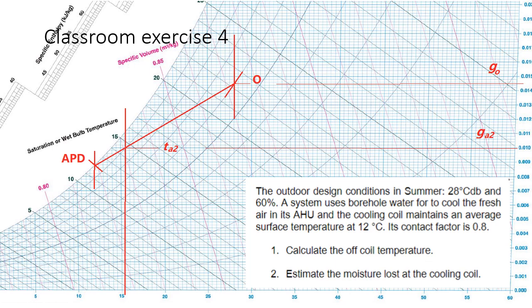Actually, the condensation happens. Now imagine if in this 28 degrees, 60% saturated, you take a can of beer out of the fridge, you immediately see the surface covered by droplets because the surface is much lower than 19 degrees, right? Anything lower than 19 degrees, you will see the condensation. So the surface at 12 degrees will surely be covered by condensation, right?